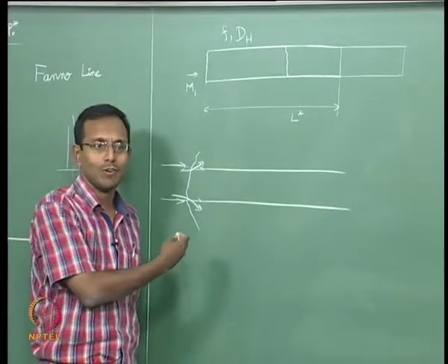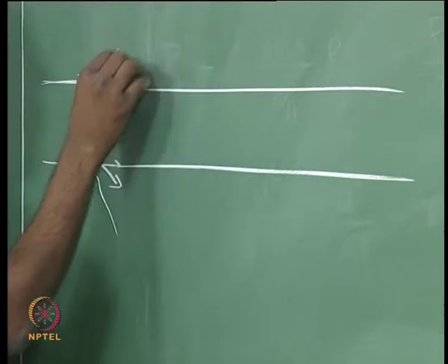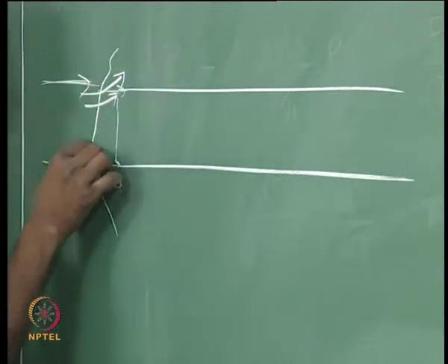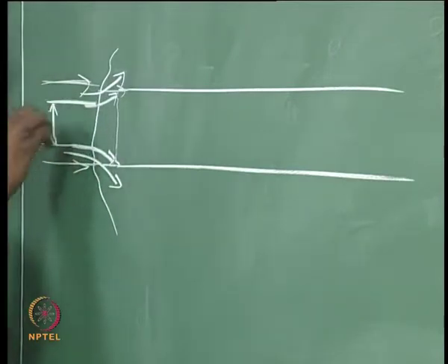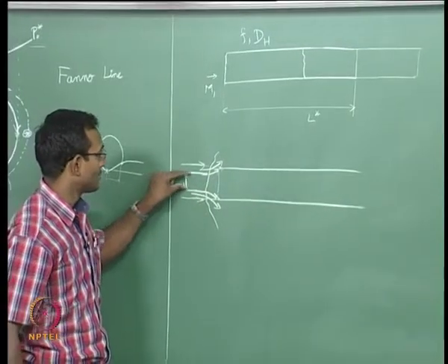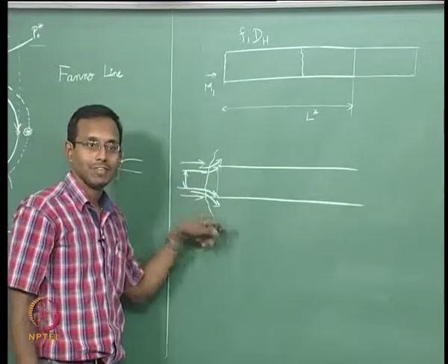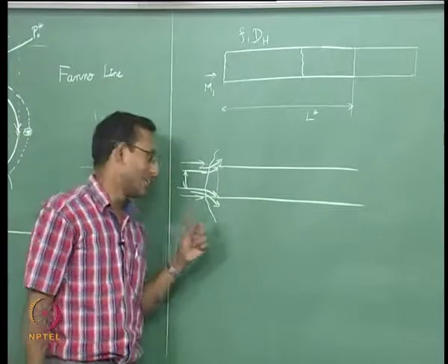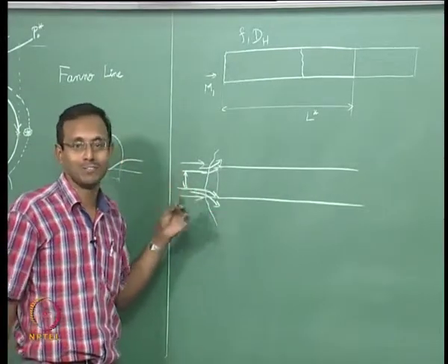You know, flow behind a bow shock is going to be like this. It is going to turn part of the flow out, because of which the mass flow rate inside will be lesser. So only the flow between this region will be going in now. So my mass flow rate has been decreased. This is called spillage. If you go to propulsion and study supersonic intakes, they will talk about spillage, and this is how spillage happens. This is one of the forms of spillage, of course.